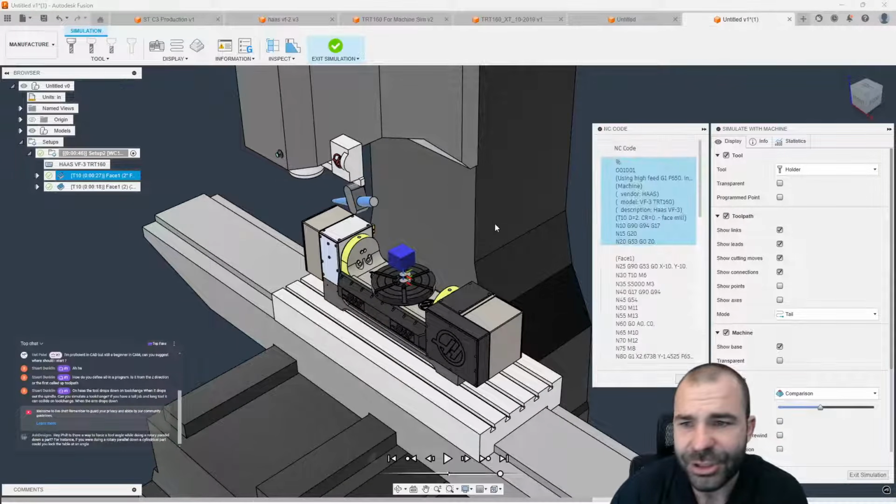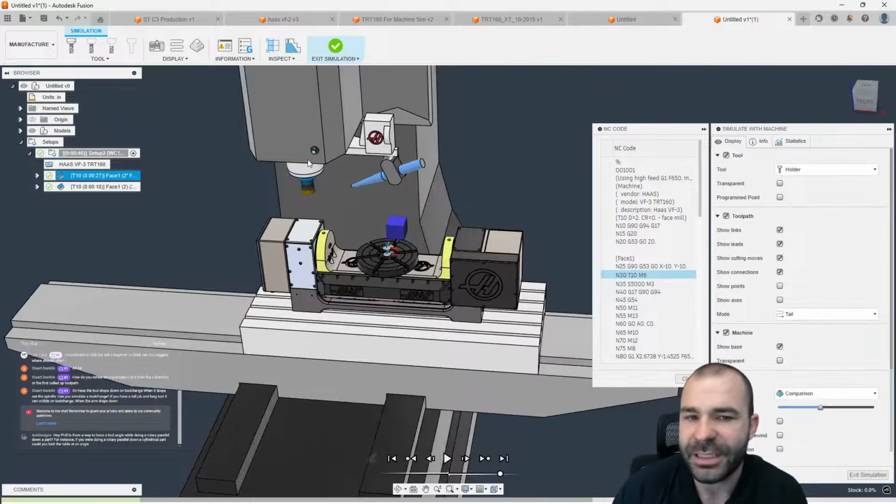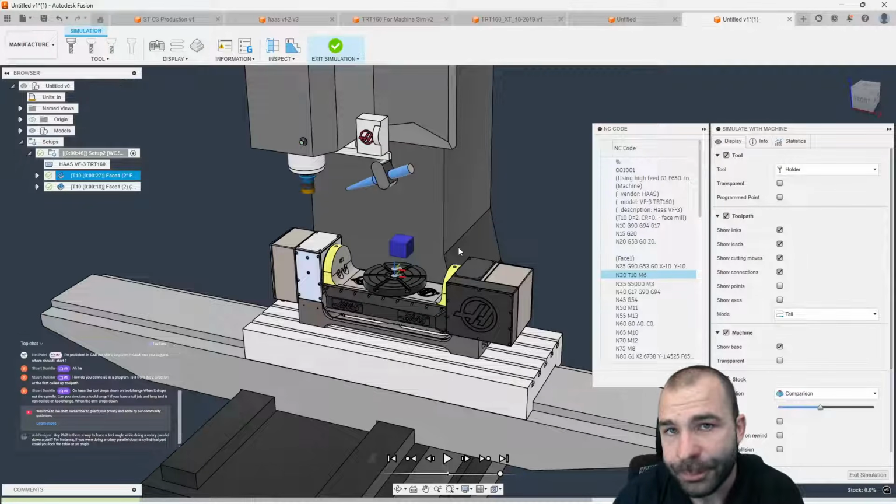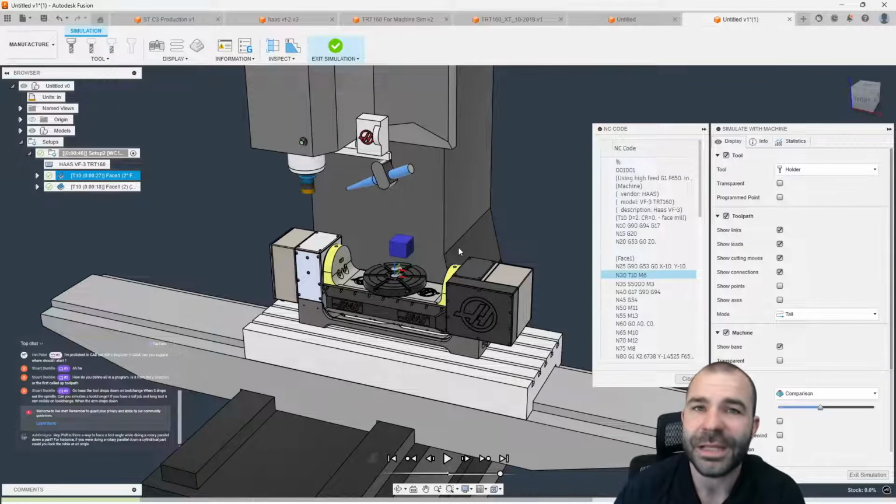So again, let's get our G-code popped up here. As you guys can see, the very first thing we have is our XY position. Now you're noticing my tool and my machine is sitting over here to the left. Again, this is where we could have added a Z home position. And for most of you with those Haas machines or old Fadals, you get about 4 inches of extra Z travel above 0. We could have also incorporated that in.